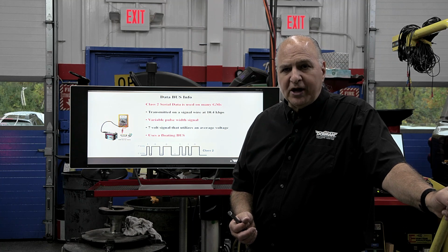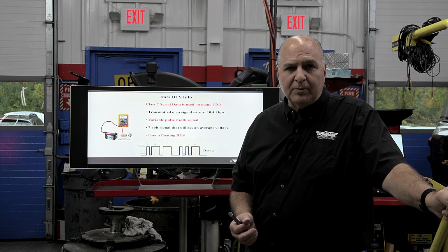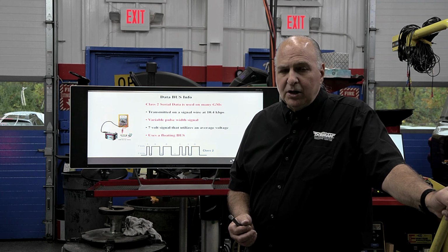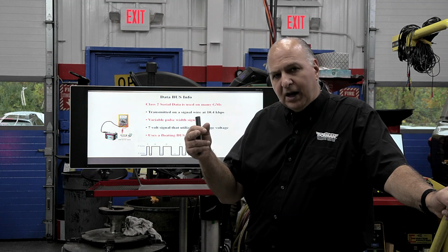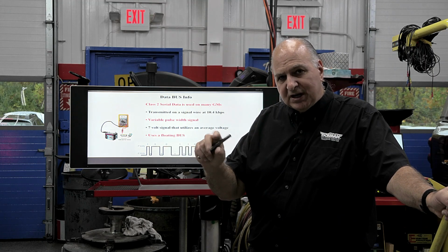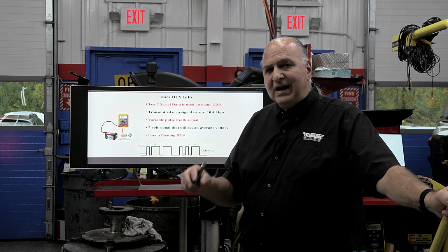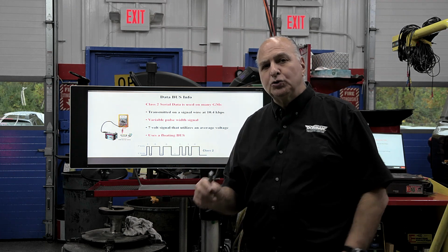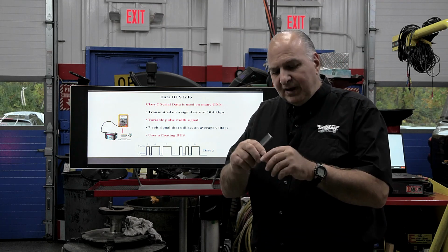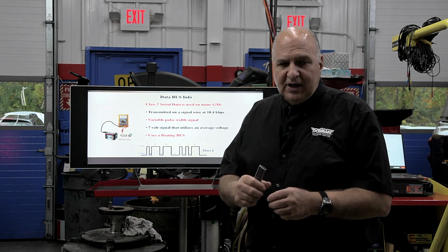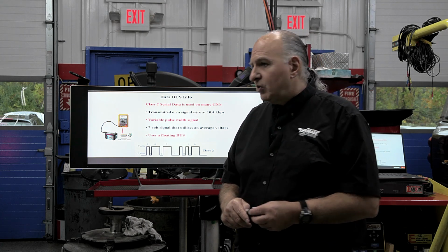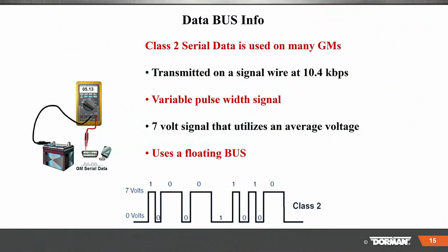Now when shielding breaks, it's like your coax cable for your TV. That could be a little dicey. You have a wire in the middle, right? And then you have the insulation, and you've got the shielding. You're going to have to connect to that shielding and go to a ground, okay? Sometimes that's difficult. You may have to take that braiding, twist it together, and make sure it has a good connection, then go to ground to keep interference off it. So let's move along here.